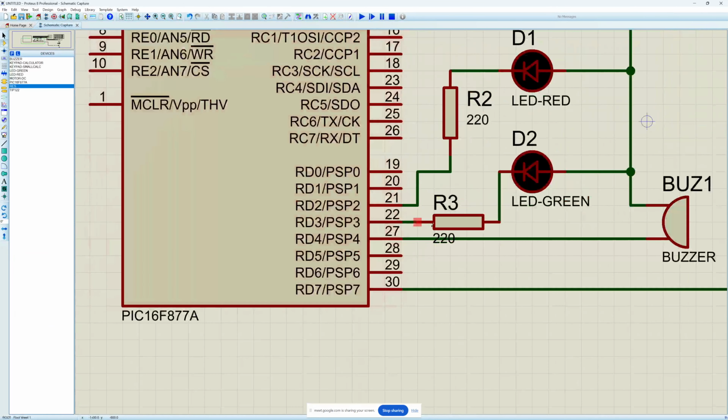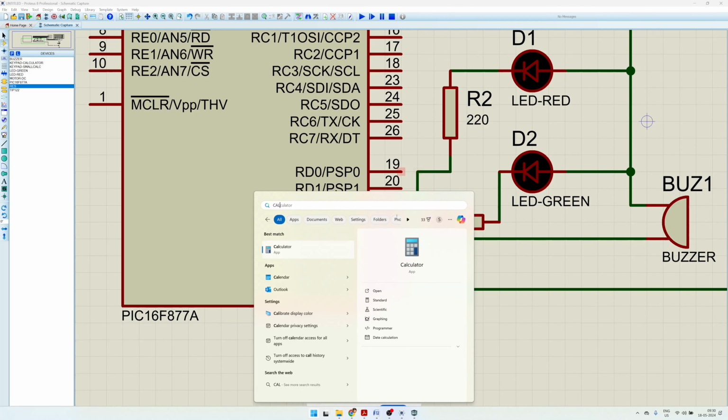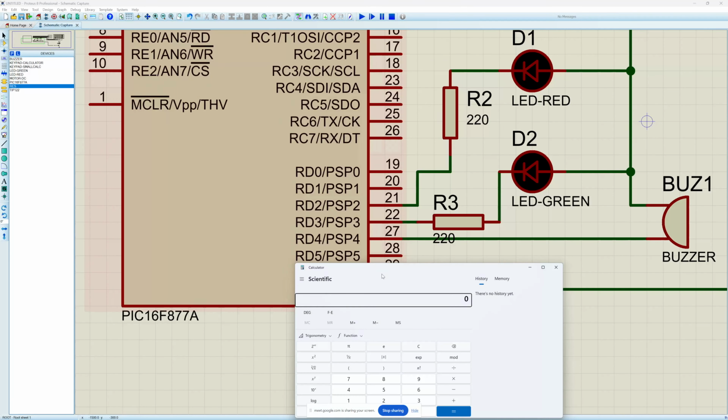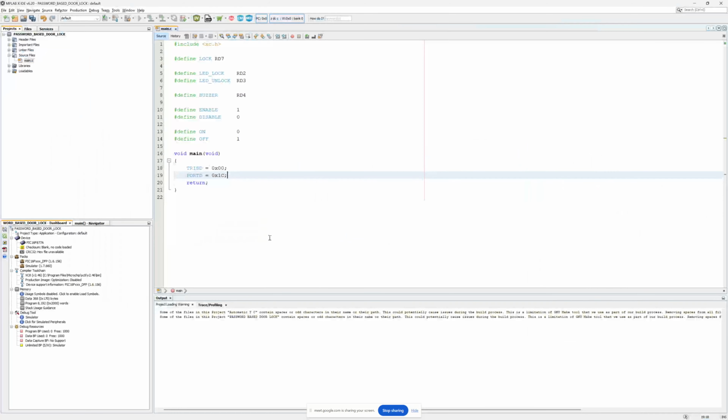See, you can see here. We need to keep 1 1 here. So 1 1 0 0. Go to calculator if you have doubt. Go to programmer. Put it in binary. Write double 1 double 0. You can see hexadecimal value C. So that's what I wrote here.